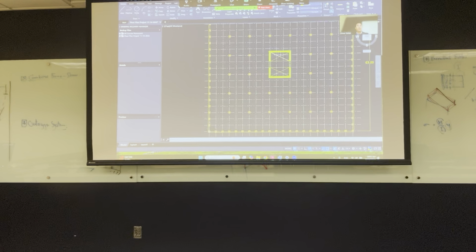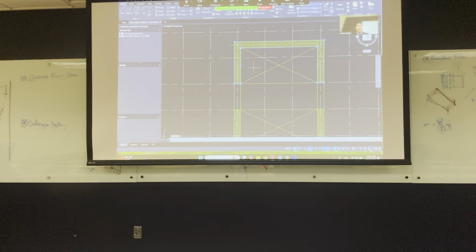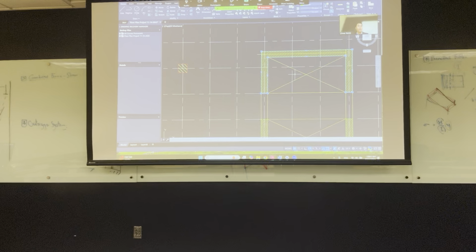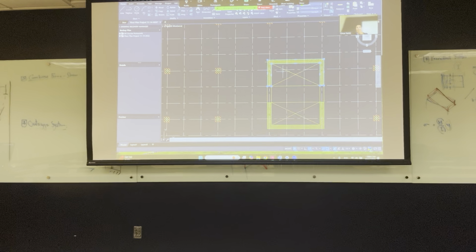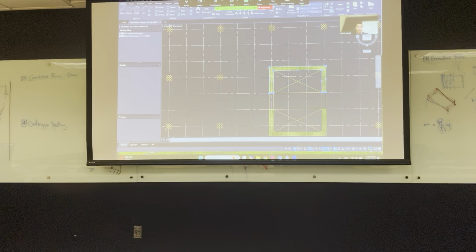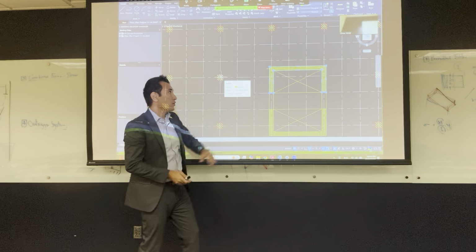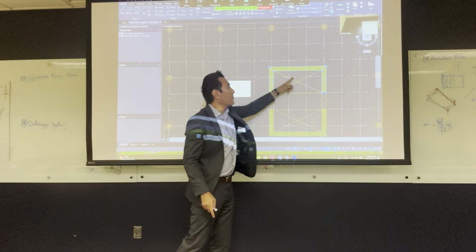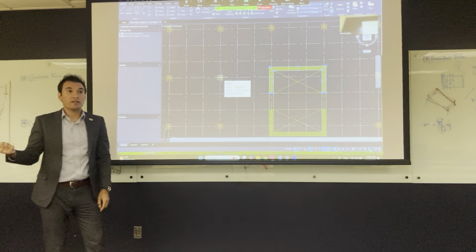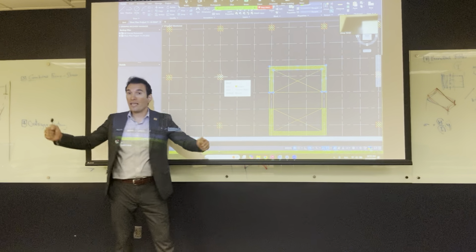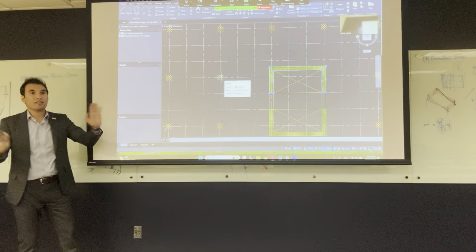And the same thing for walls. I can actually make a polyline and make the shear wall. So the shear walls are really huge. If this is 3 meters, then we have 12 meter by 12 meter shear walls. All right, so we have this. Try to make this wall in the same line with these columns. It's gonna be much better than the way that I have it here. So maybe you make the shear walls on the same axis. Why? Because you're gonna build an outrigger system, and it's better to have the outrigger system cross columns and cross the shear walls, so it can work effectively. But if you wanna keep it like this, that's fine.